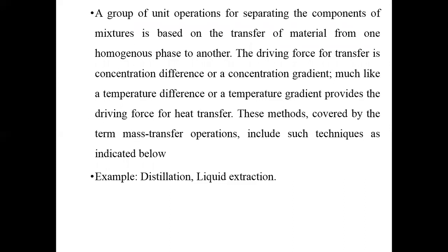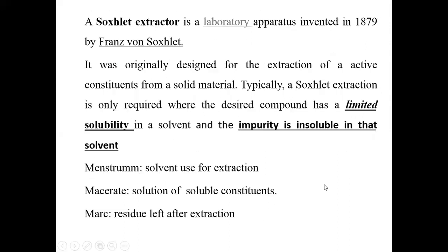A group of unit operations for separating the compounds of a mixture is based on the transfer of material from one homogeneous phase to another. The driving force for transfer is concentration difference or concentration gradient, much like a temperature difference or temperature gradient provides the driving force for heat transfer. The methods covered by the term mass transfer operations include techniques such as distillation and liquid extraction.